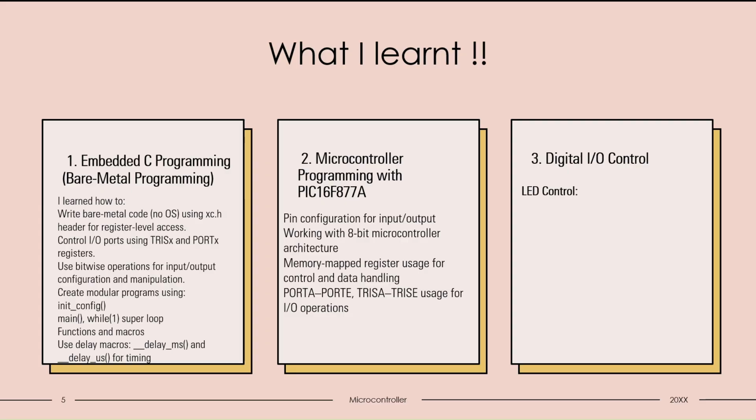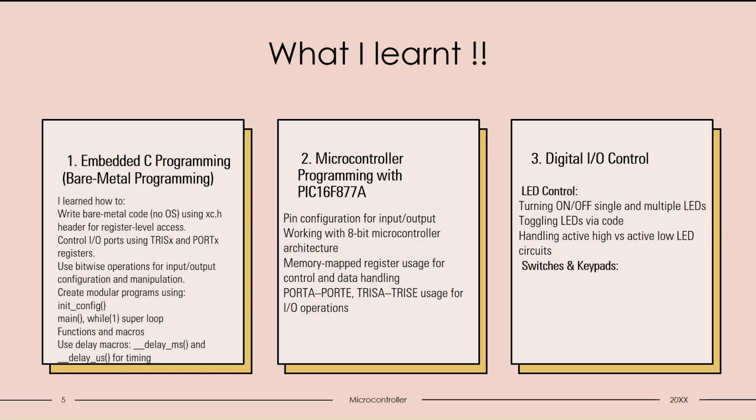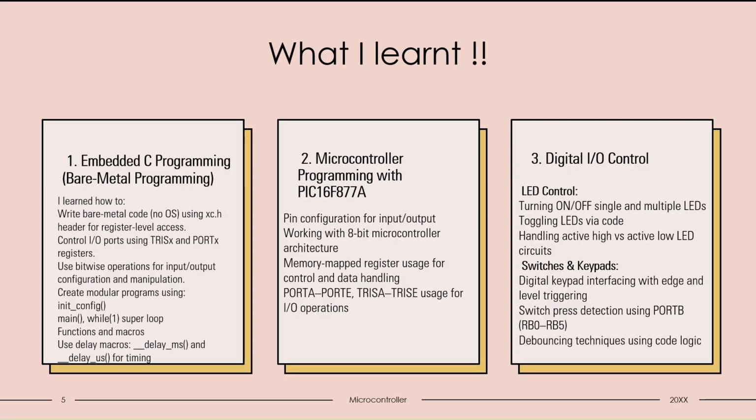We saw many peripherals like LEDs, buzzer and fan: turning on single and multiple LEDs, toggling LEDs via code, handling active high versus active low LED circuits, switches and keypads, and digital keypad interfacing with edge and level triggering, switch press detection using PORTB RB0 to RB5, and debouncing techniques using code logic.